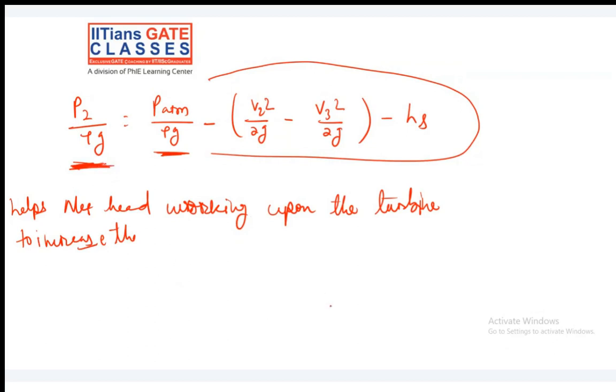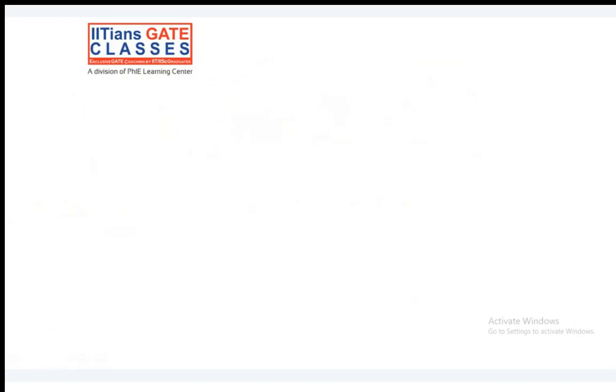Because initially in the Pelton turbine you were able to extract between the given pressure and the atmospheric pressure, but here you have the freedom to go even below the atmospheric pressure. So that is why the efficiency and the power of this Francis turbine will be high compared to the Pelton turbine for the given energy input. Okay. Now, what is draft tube efficiency?